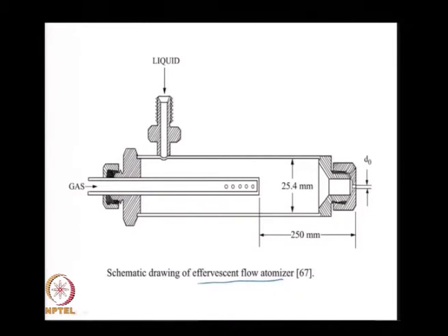The design itself is where you have a liquid coming in through the side of a nozzle, and it flows in through this annular passage, and at the exit here you have a gas being injected into this liquid through a series of holes. In fact, another design could be to extend this all the way down to nearly the exit, but this piece is a porous piece.